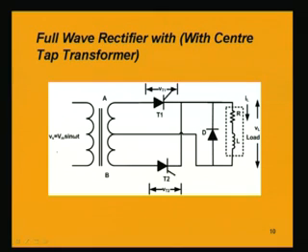the thyristor which will be conducting is the upper one, because in the positive half cycle of AB we are considering this secondary side of the transformer and we will be analyzing the waveform. Let us consider the voltage across AB. Now, the point A, when it is positive with respect to B, it is a center tap transformer, so it will be plus and it will be minus. This point is the ground, or center point is the ground.